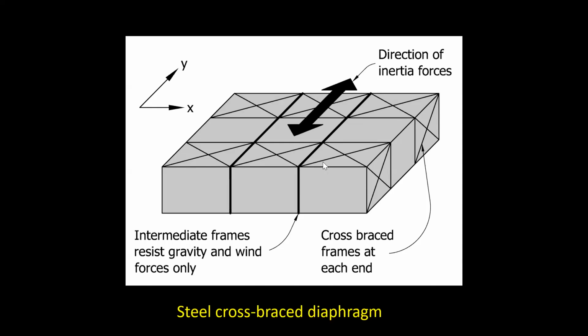The trusses act like horizontal beams. And so for every wide span structural roof you design, you also have to show this horizontal truss to transfer the loads sideways.